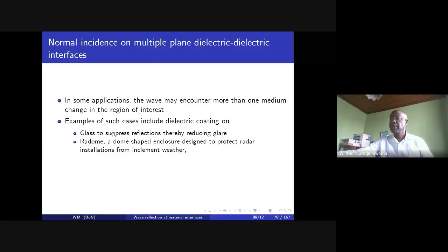But once you have introduced a boundary between the antennas and the equipment, your signal will be reflected at those walls before it arrives at the radar. And since you want all of it to come to it, you must reduce the reflections from the enclosure.